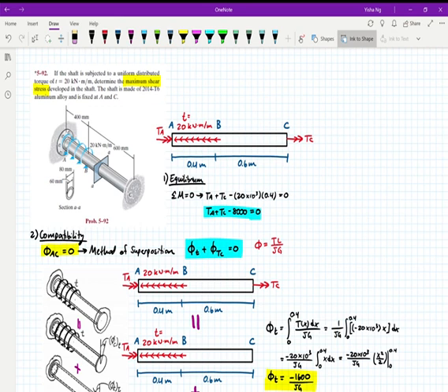One other thing to notice, your cross section here is that your shaft is actually hollow. It's all one material, but it's hollow in the middle, and that's going to be important later when we calculate the moment of inertia. Okay, so I've done what I did on the last problem and just done a straight on 2D view. Honestly, I'm not exactly sure how to draw a distributed torque, so I just did that. I hope it's pretty clear that it's just a torque that's acting over the section of AB.